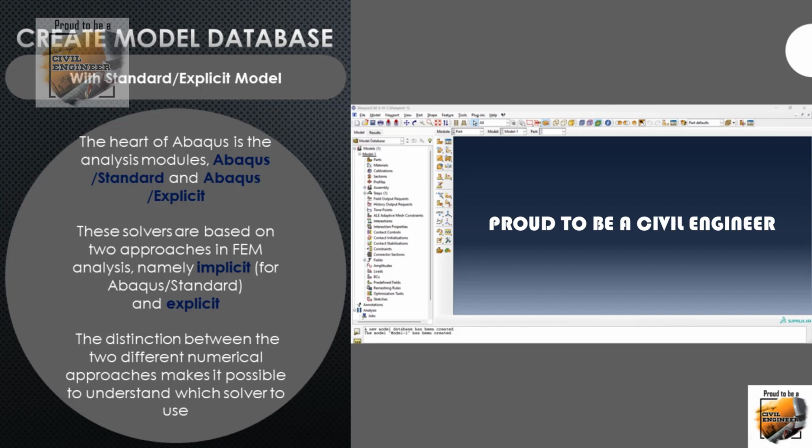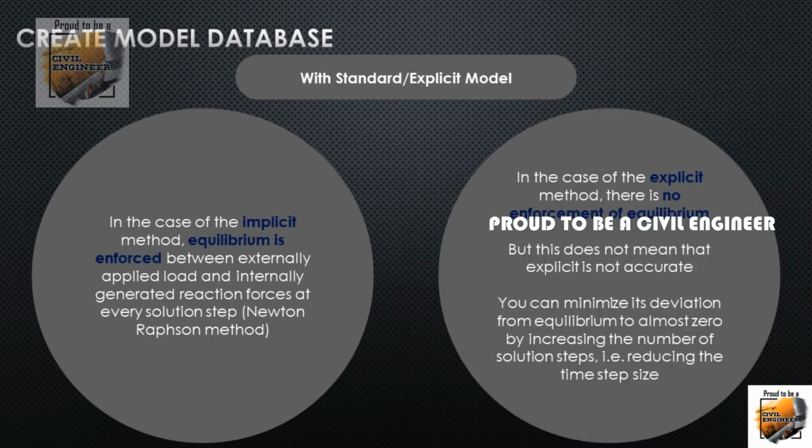These solvers are based on 2 approaches in FEM analysis, namely implicit, for Abaqus Standard, and explicit. The distinction between the 2 different numerical approaches makes it possible to understand which solver to use. In the case of the implicit method, equilibrium is enforced between externally applied load and internally generated reaction forces at every solution step, Newton-Raphson method.